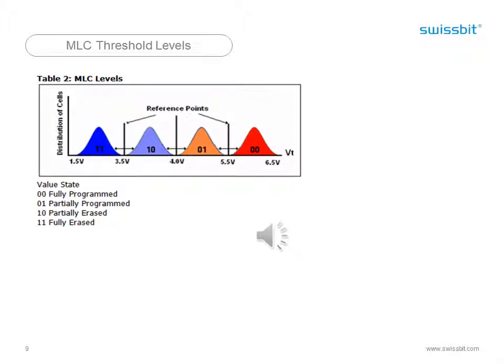As previously seen in Figure 1, a flash cell's ability to store charge is also why MLC technology works. Since the range between each bit cell has decreased for MLC, the sensitivity to an accurate read also increases. Thus, more rigidly controlled programming is needed to manipulate a more precise amount of charge stored on the floating gate.